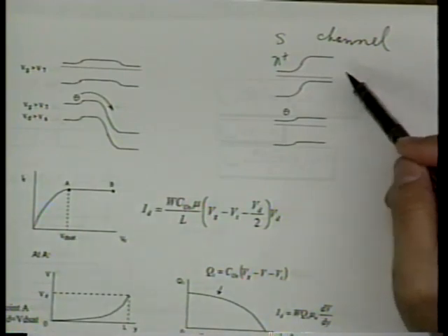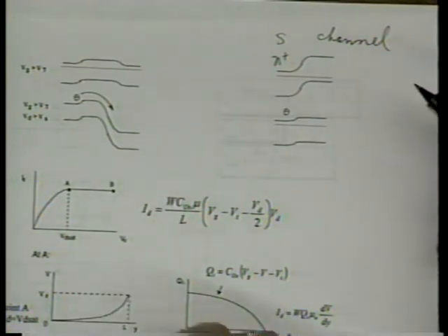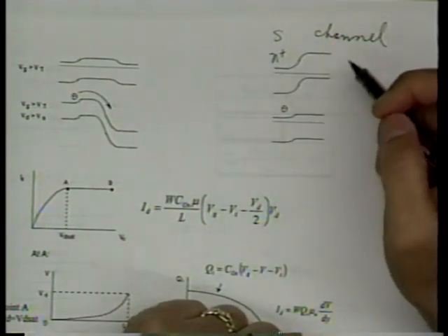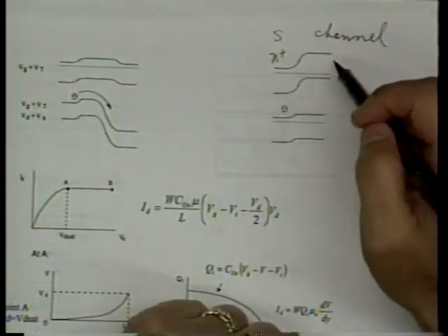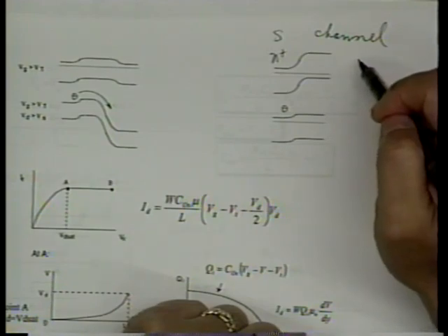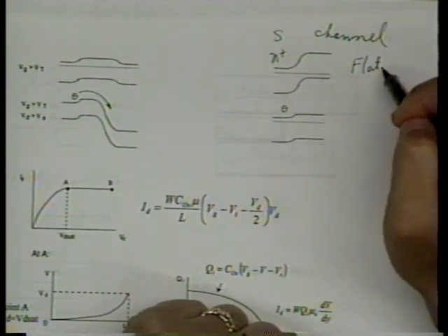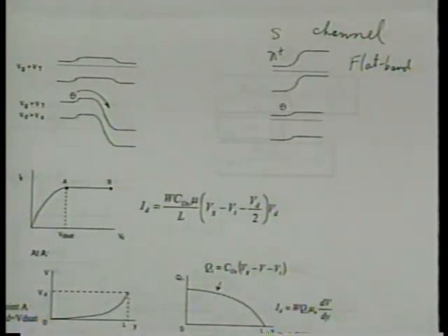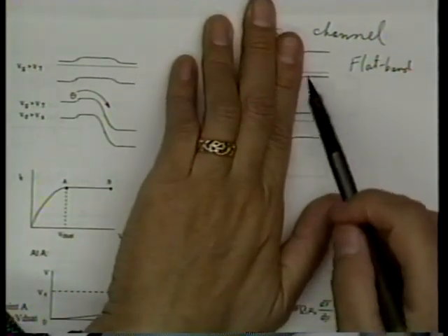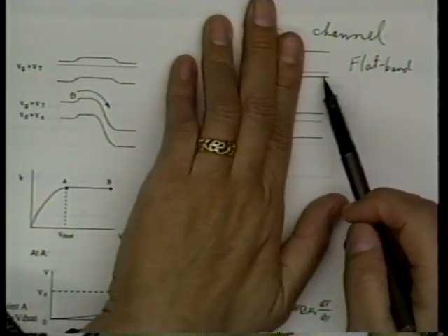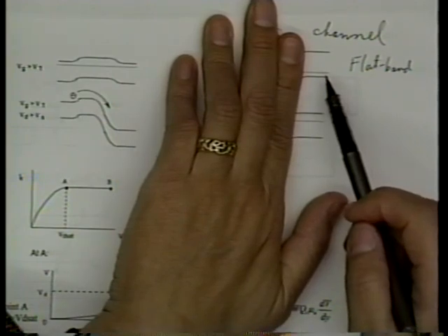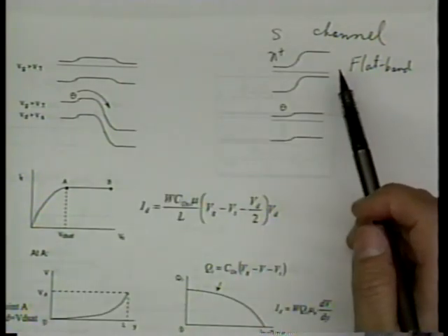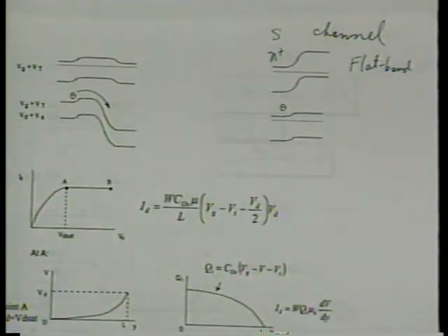What we are drawing here, you probably would guess, is appropriate. We did this for the so-called flat band condition. It may not be clear to you, but it's for flat band. If we draw this for the flat band condition, then the Fermi level for the channel portion is exactly where you would be in an equilibrium p-type semiconductor. That's kind of where you'll see.